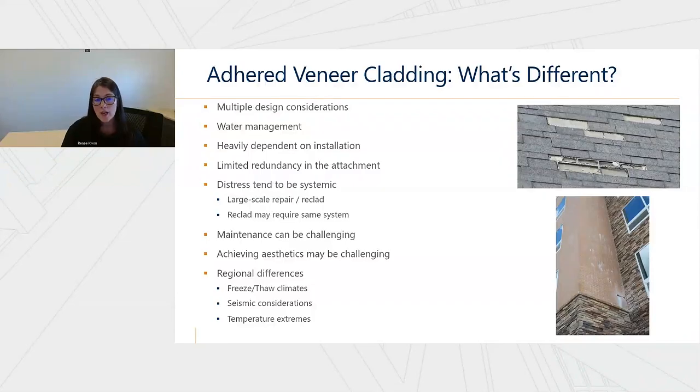So with our adhered veneer claddings, we're more relying on either a barrier system or a water managed system. A barrier system being that we're preventing that water from entering the wall system, whereas with a water managed system we accept that some water is going to enter our wall system, but we have a means for managing that water. These systems are going to be heavily dependent on installation.